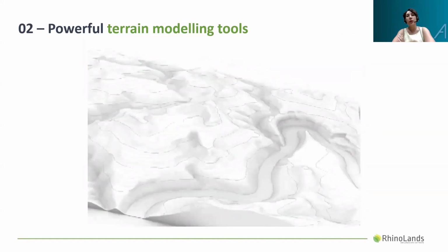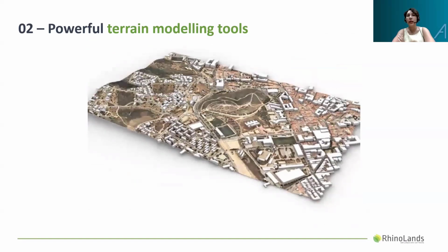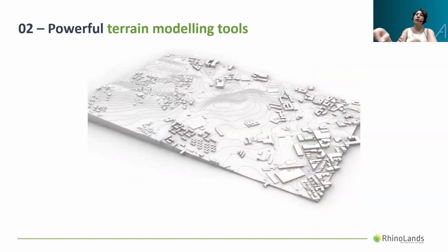We can generate the terrain from digital elevation models, DEM files, or generate a terrain just by indicating the location on the map. The program uses a global elevation database to produce the 3D terrain of the selected area.